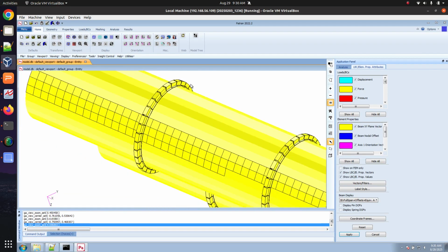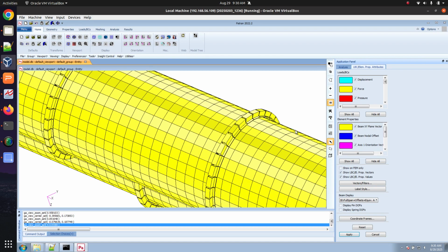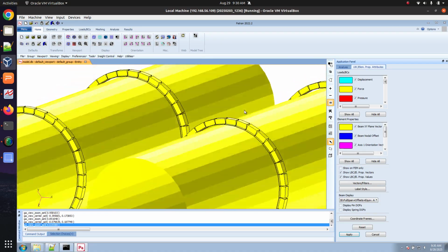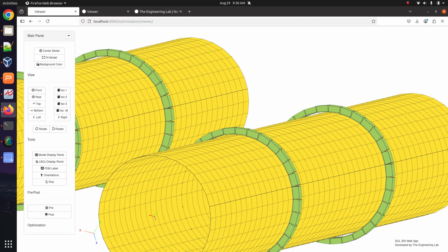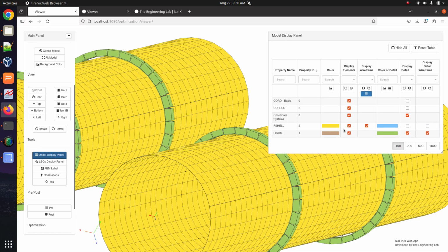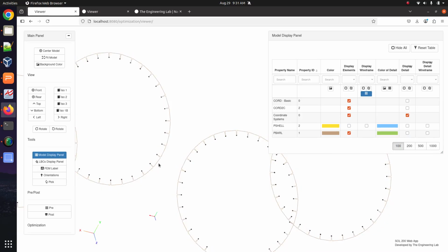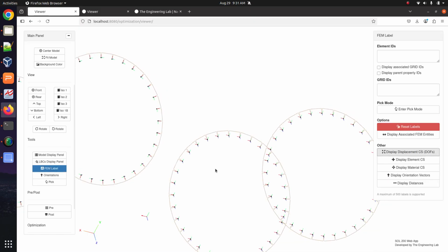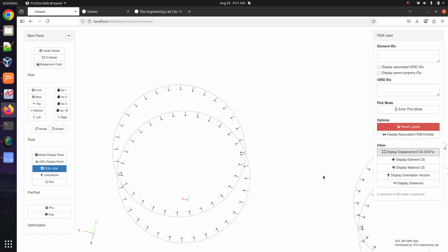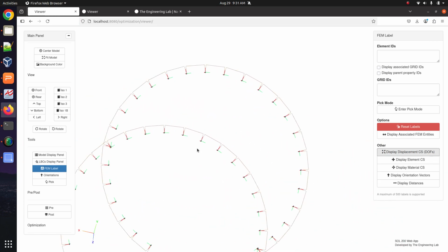If you recall earlier in this video, we started off with really oddly oriented beam elements, but here we took the time to modify those beam orientation vectors. So let me do a quick summary, and then I'll show you a few additional capabilities in what we discussed today. Whenever you define a vector, it's very important to ask in what coordinate system the vectors are being defined. So here we realize that those beam orientation vectors are often being defined in the